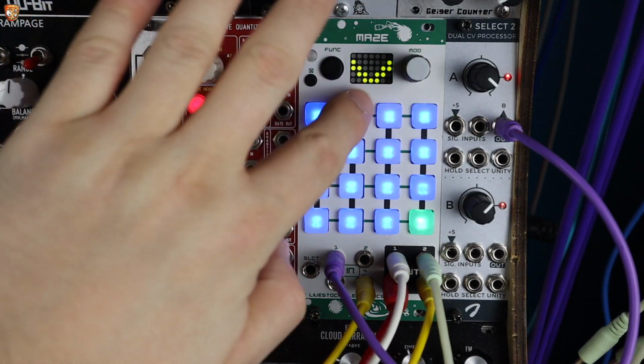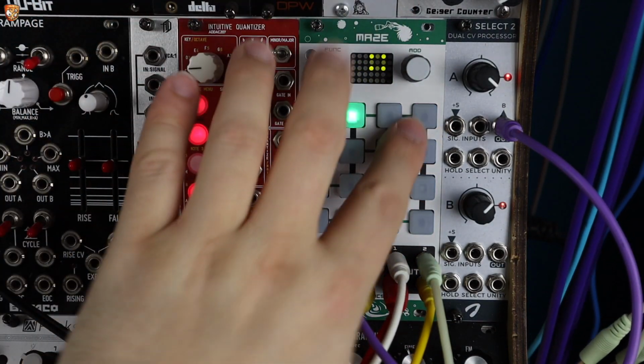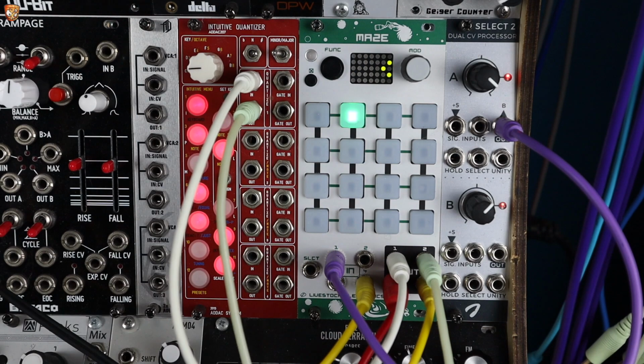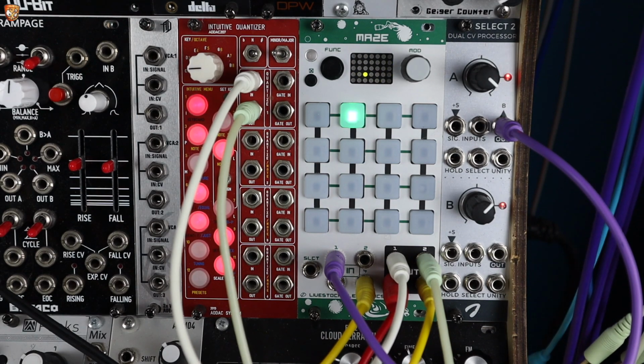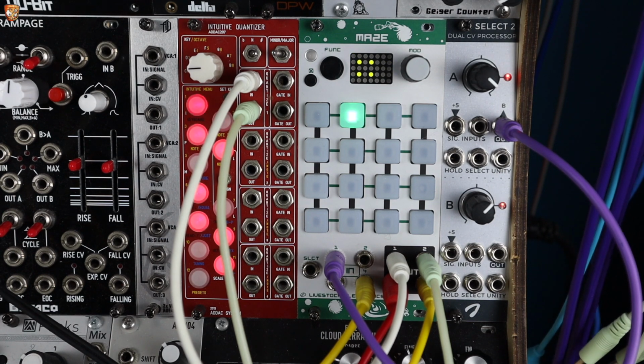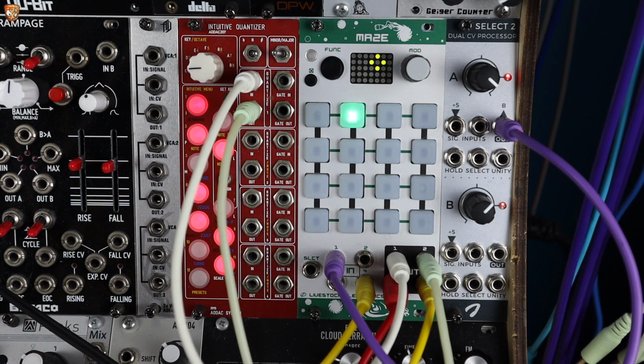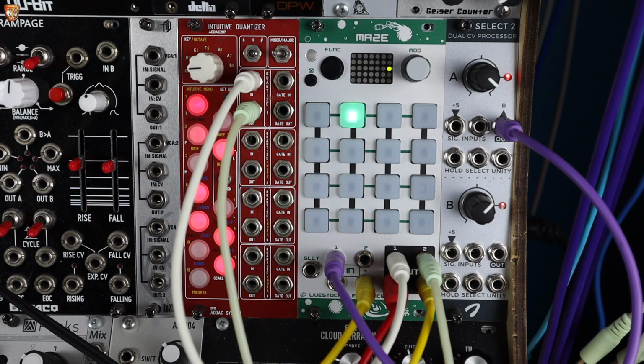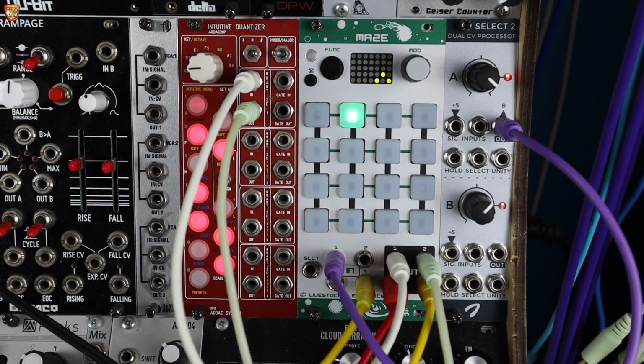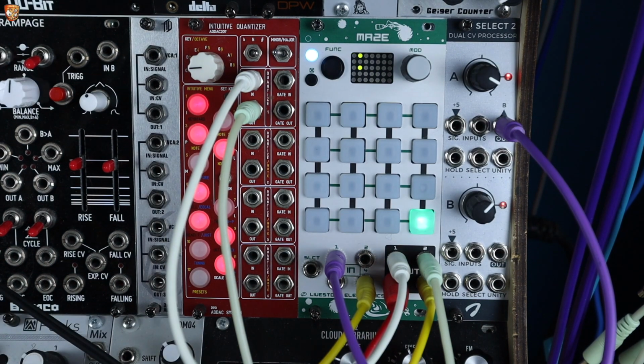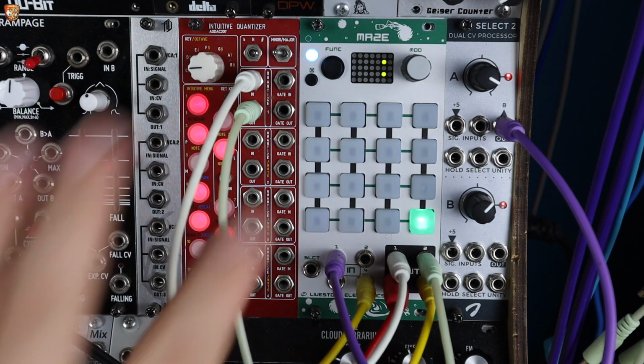So this is going to be like a single note per state with independent low pass filter modulation depths, a stepped voltage out to the high pass filtering, a stepped voltage into the quantizer, and a stepped amount of reverb that's going to be controlling its spring reverb from that stepped voltage. So let's set up a sequence. So now I've got 16 different states for the depth of modulation over the low pass, the pitch, the reverb amount, and the high pass filter cutoff.